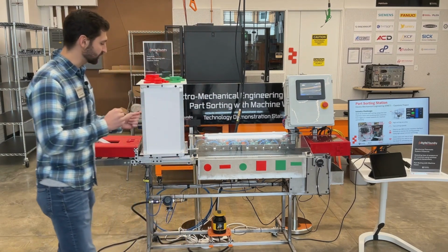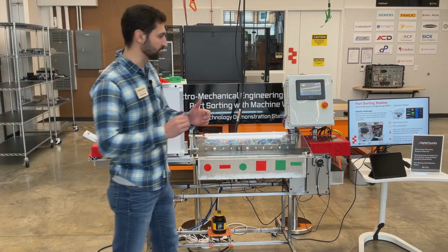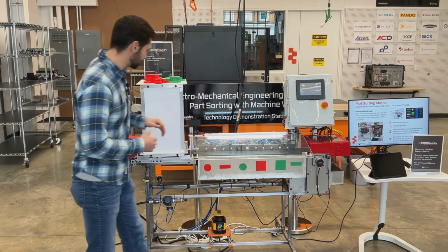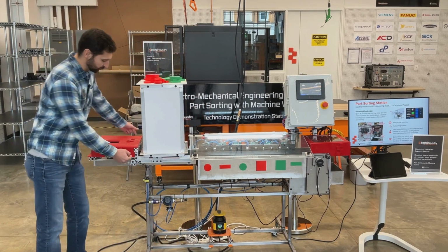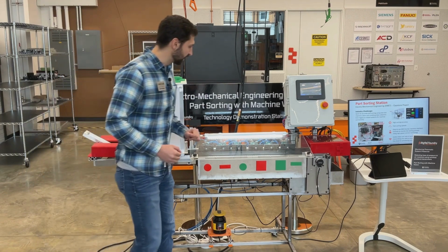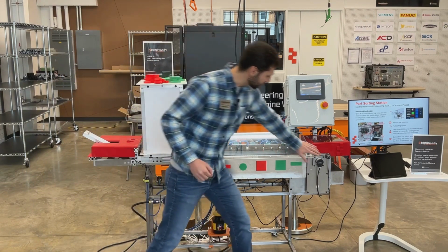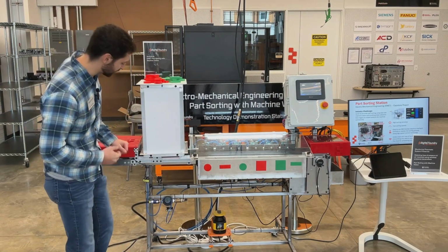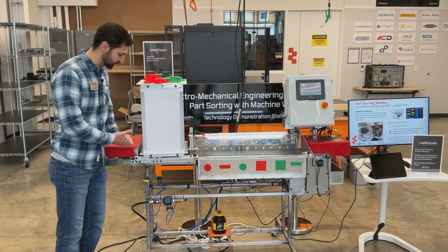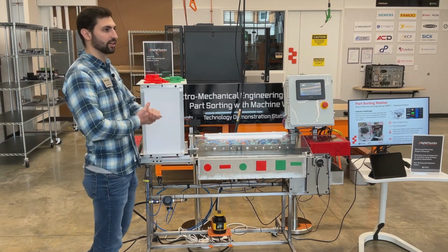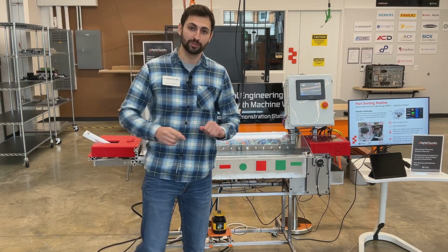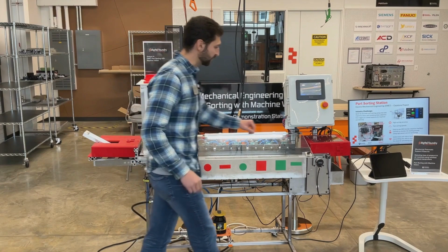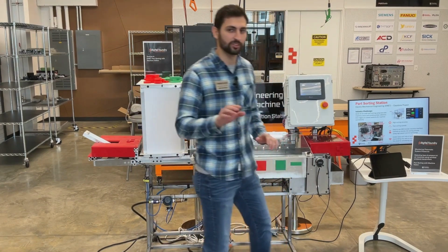We use this as well as a legacy device, so you might notice the original sensors that are on here, such as a through beam sensor over here and the encoder on the conveyor over here. But we added some stuff with it being a legacy device. We added a pressure sensor, which is an IIoT device connecting to a hub that you can't see on the wall over there, as well as a distance sensor over here that will detect bad parts.